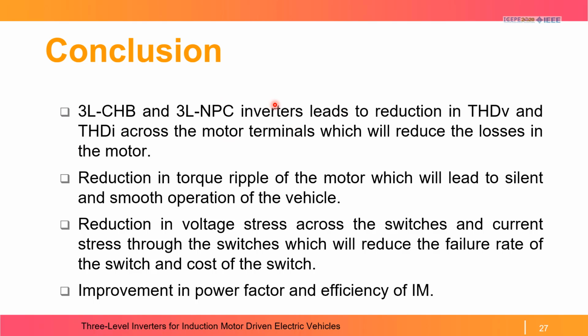The 3-level CHB and 3-level NPC inverters lead to a reduction in THD of voltage and current across the motor terminals, which will reduce the losses in the motor. Reduction in torque ripple of the motor will lead to silent and smooth operation of the vehicle. Reduction in voltage stress and current stress on the switches will reduce the failure rate and cost of the switch. There is also an improvement in power factor and efficiency of the induction motor with 3-level inverters.